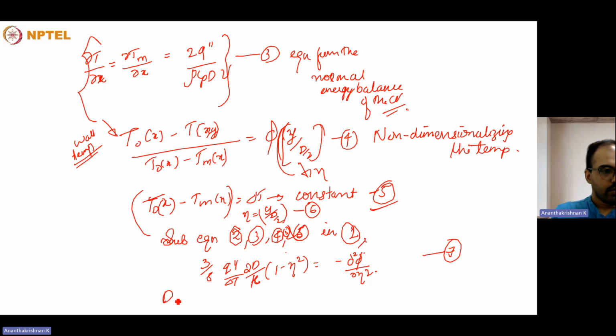So the hydraulic diameter is equal to 2 times the width, and we could write the Nusselt number equal to the heat flux into hydraulic diameter dH divided by k into delta T. So this is basically how we get the Nusselt number equal to h into hydraulic diameter divided by k, where h into characteristic length divided by k, the characteristic length will be equal to the hydraulic diameter, and h could be written as heat flux divided by the temperature difference, that is T of wall minus T mean temperature.